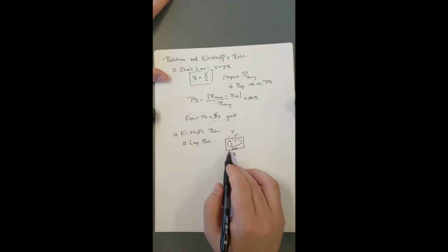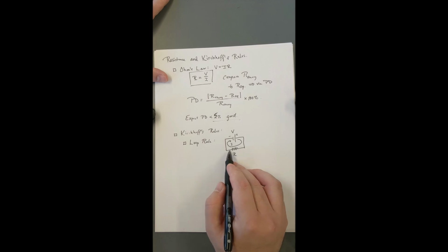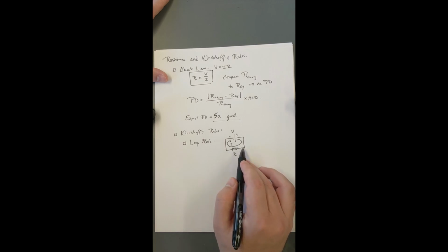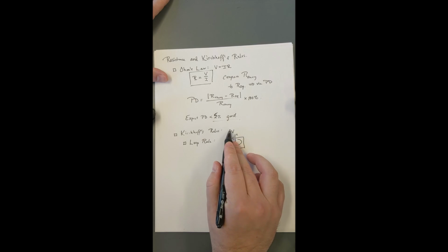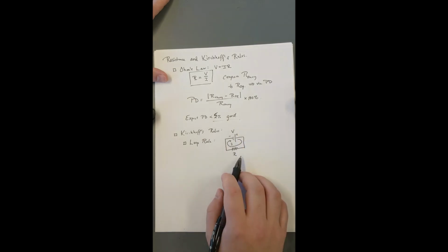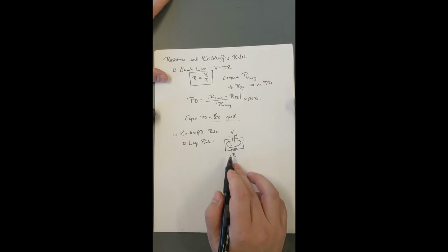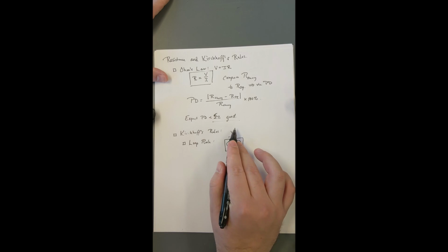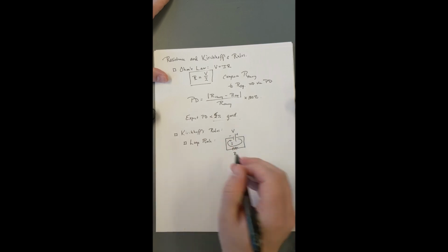And you'll see this as if we put more resistors in series with this particular resistor, we'll see that the total voltage across all the resistors must equal the total voltage that's being supplied. And certainly you can just add up the individual voltages of each of the resistors that we find, and hopefully we come out to something that is approximately equal to the voltage being supplied.